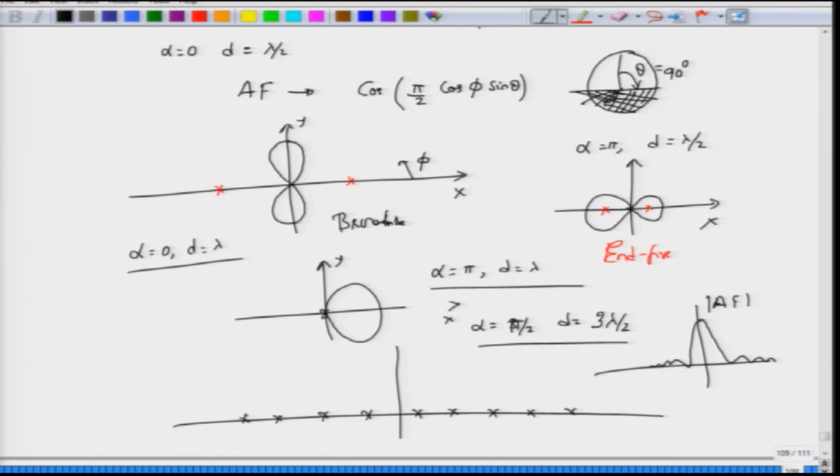Okay. So, we are basically taking all these partial waves in such a way that the maximum energy is oriented in a particular direction, and the side lobes can be minimized as much as possible. Okay. By adjusting the phases differently, you can also get different types, but this would be a nice focused antenna that you can actually have, right.